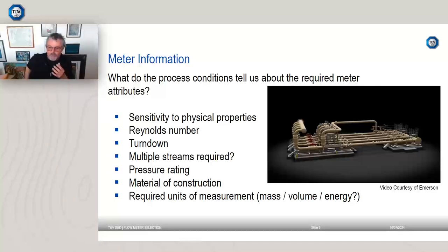If I'm using hydrogen as a fuel or natural gas as a fuel, it's actually the amount of energy that I'm interested in, not necessarily the volume that energy occupies or the mass of that energy. That's probably less applicable to hydrogen because my understanding is that hydrogen will be very pure. So you could infer the energy from the volume or the mass. But for natural gas, it's very common to want to trade in energy. And as we'll see later on during the additional equipment section, that requires a lot of extra cost, equipment, and space.